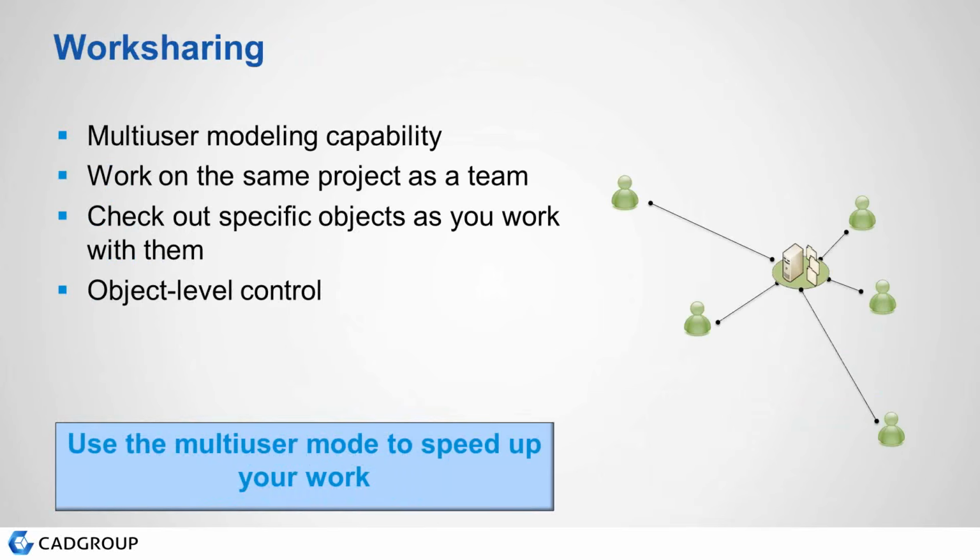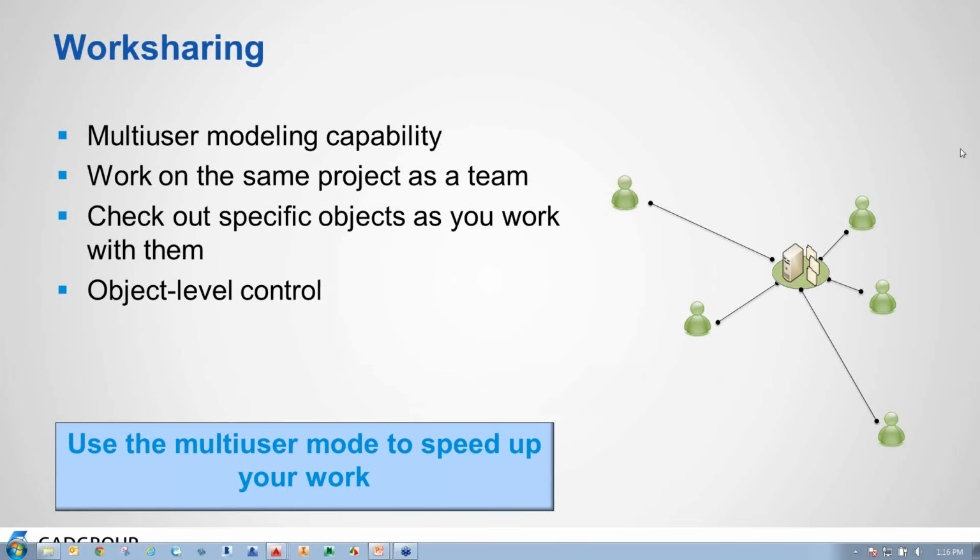Work sharing, again, is something really important for large mining jobs. We won't have a single person doing the entire hundreds of tons of steel modeling and detailing. We'll have different people in the team doing different areas or zones of that job. In that case, we can also do work sharing. In work sharing, I can pick a part of the project and check it out for my use. Once I check it out, I can work on it. I can also do a partial work sharing wherein I've got a column that goes from level 1 to level 3. I can do a partial sharing, so I can add connections to it and insert holes, and so can my colleague who's working on a different level.